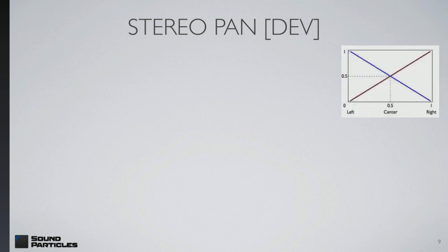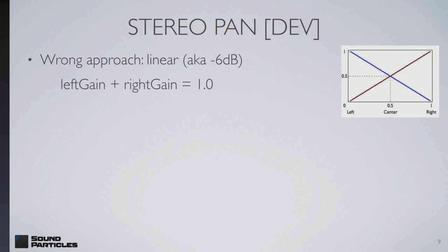So now imagine that you want to create something simple like a panner. Okay, how can I do that? Your first idea would probably be to create something like this. You have a left and a right, and you simply do a linear curve between them. This is probably not the best approach, unless you are too worried about mono compatibility, because essentially what you want is to make sure that the power coming from the speakers continues exactly the same as you pan sound around.